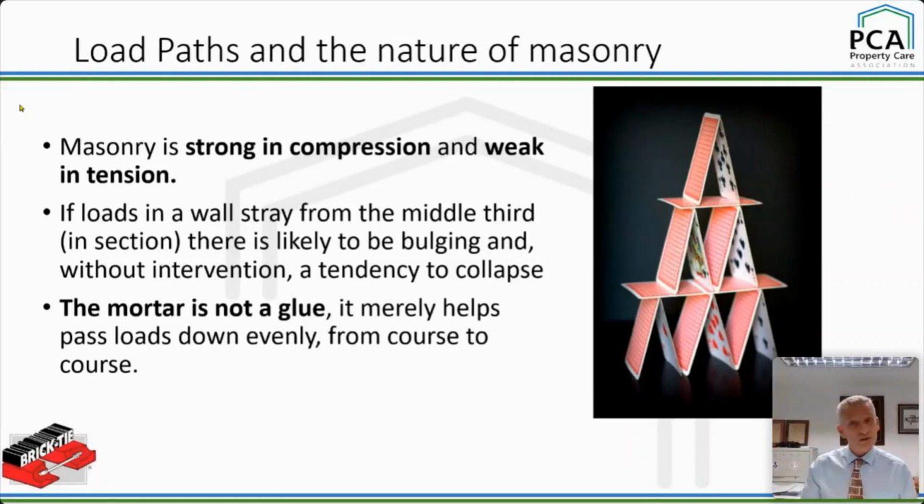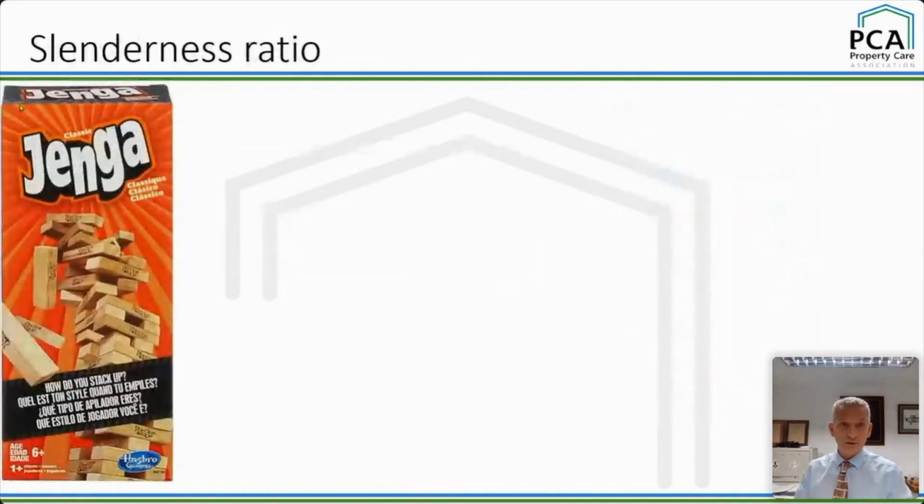And the third point, there's loads of points, but we just want the most important ones, is that the mortar is not a glue, all right? Mortar's role is not to glue all the units together. That's not its purpose. Its purpose is simply to transfer those vertical loads from the top of the building down to the bottom evenly from course to course to course. Actually, that also works at an angle in an arch when we've got compression. If those bed joints are not evenly full of mortar, then the forces are uneven and they can change and become eccentric.